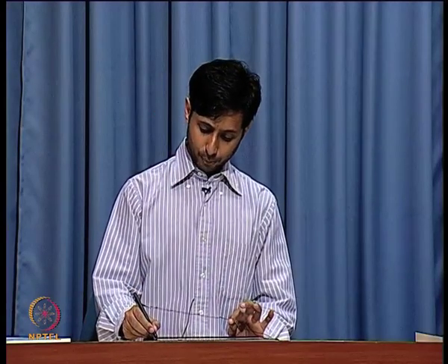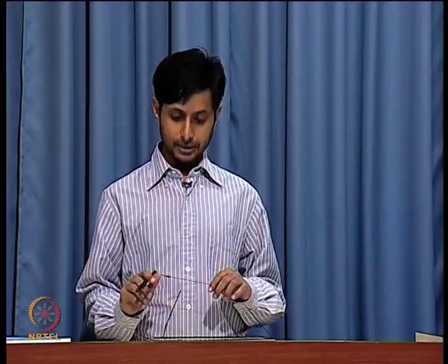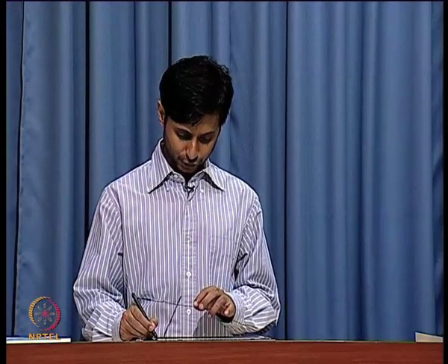The junction capacitance is proportional to the area of the source plus the perimeter of the source times the height of the junction of the source, and it is inversely proportional to the depth of the junction. Now, the depth of the junction gets modulated with voltage, that is all you have to remember.